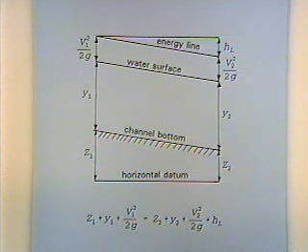And the real problem that we have and never really have been able to work out in the last 100 years is the head loss term. And so what we do with the head loss term, we use Manning's equation. Now granted, Manning's equation is a uniform flow equation, and we're solving non-uniform flow problems when we're doing gradually varied. And gradually varied means there's no hydraulic jump or hydraulic drop problems. But for this one term, the head loss, we'll use Manning's equation to estimate the head loss.